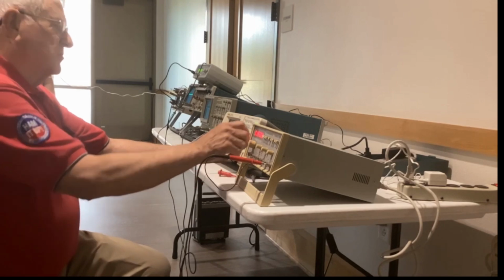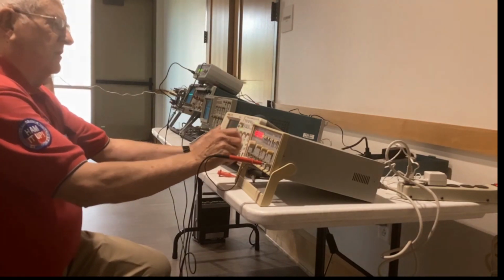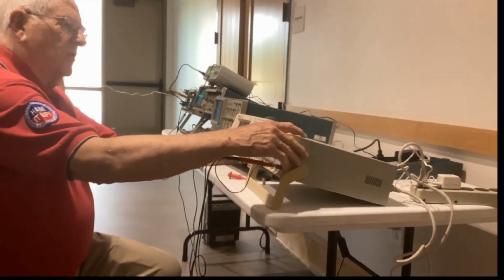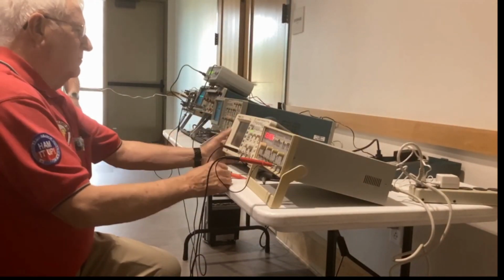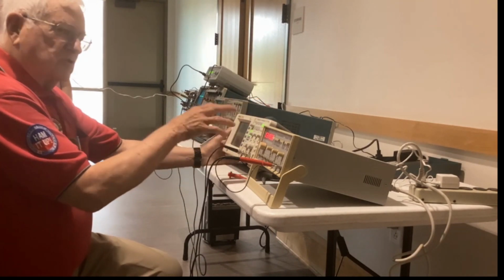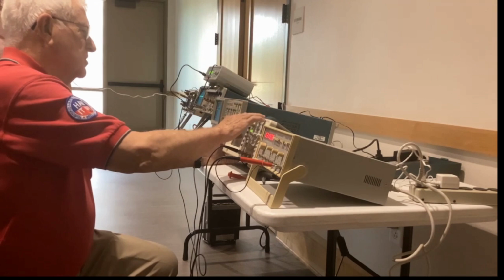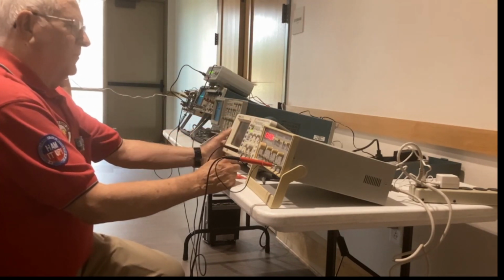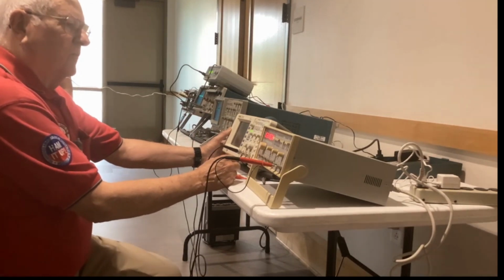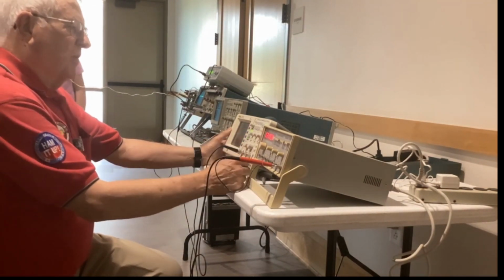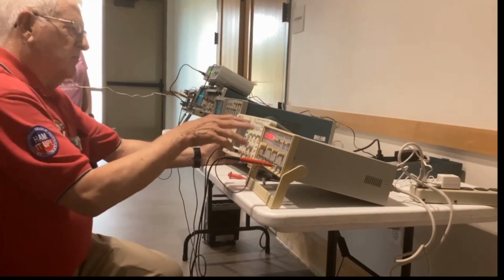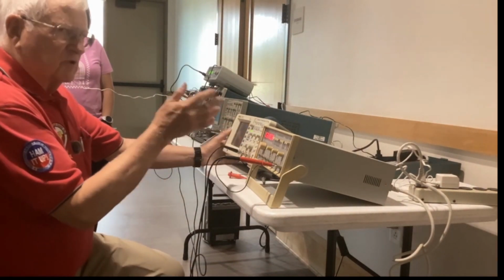And again, actually, we can tweak it and see where it goes. And then we want to go back up to that one. Boom, we're way up there. Now let's go auto again. Auto basically just adjusts the trigger levels and all that stuff to give you a good display, so you don't have to mess with it. So there we go. And now we're running at 2.18 megahertz. We're supposed to be able to go to 2 megahertz, so we're pretty much maxed out right there. And the two are pretty close. Considering neither one of them's calibrated, that's not bad.